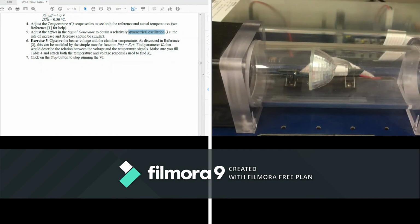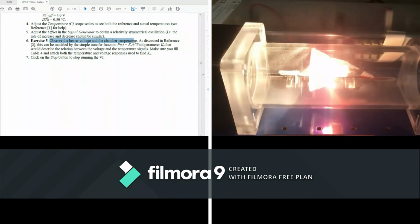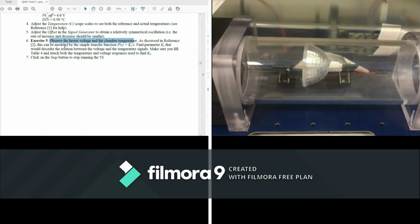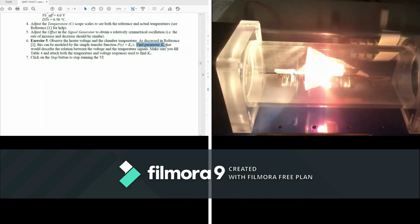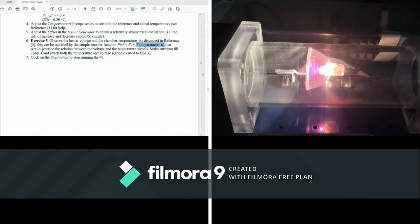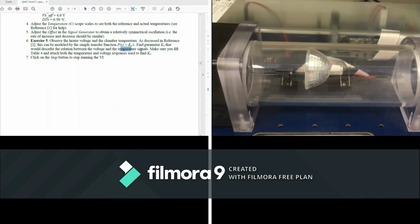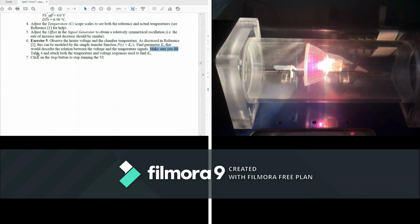Now exercise number 5, we want to observe the heater voltage and the chamber temperature as discussed in reference 2, which is the manual control guide, and we want to find the model gain kV that will describe the relation between the voltage input and the temperature output. In order to find kV, you need to fill table number 4.